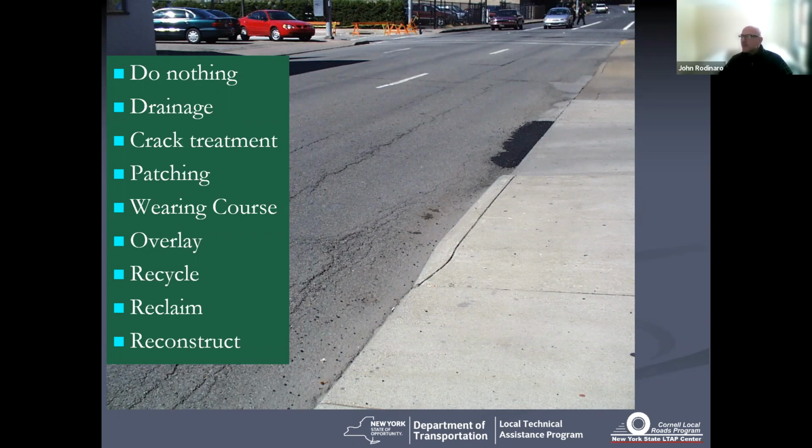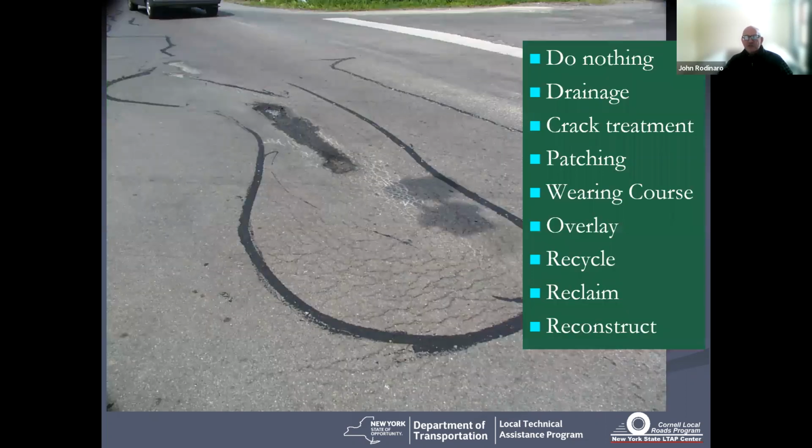We had patching, overlay, and reconstruction in the choices, but I think it depends on what the structure is. This one would actually make a pretty good fill in. Yep, the mill and fill would be my choice. Yeah. All right, in terms of this one, looks like somebody was already thinking about patching.